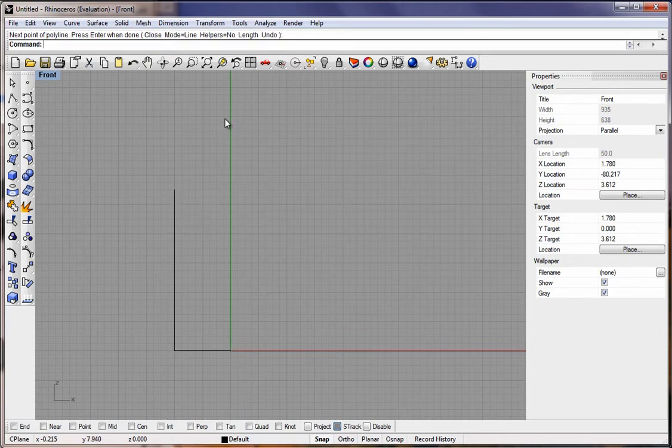Right click, and then up here, at about 1, 2, 3, 4, 5, 6, 7, 8. So right about here, we'll go ahead and add another polyline for the top of the bottle. And now you can use the interpolate curves, and we're going to go with start tangent off of this point here. Click and drag it up and in, move it up again, over, and then end tangent at that point there, and drag it straight up.